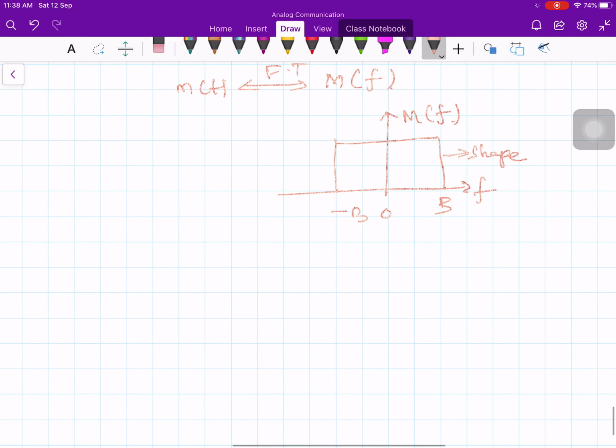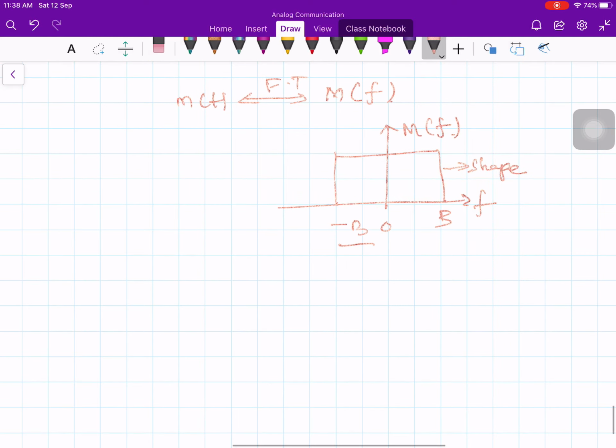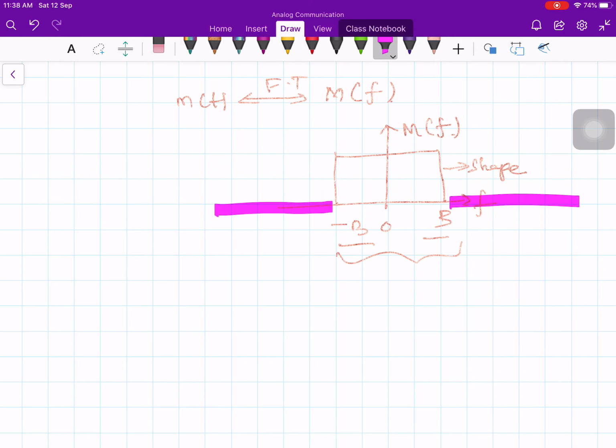Now I want to show the carrier component a little more clearly. So let us see how it looks. Now you can ask a question, why do we call... no, before that let me finish this. Suppose your message waveform has a spectrum, say minus B to plus B. This is the Fourier transform, and it is non-zero between minus B to plus B and 0 afterwards, that is, for mod of f greater than B.